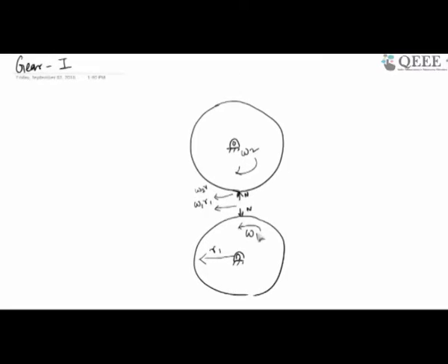So this driving member is trying to move in this direction, which means there is a resistive force mu n. Mu n is the friction force that is acting, which is trying to resist that motion. But because of the action reaction pair, there is a mu n that is going to get transmitted to the other member, that is mu n here, right.